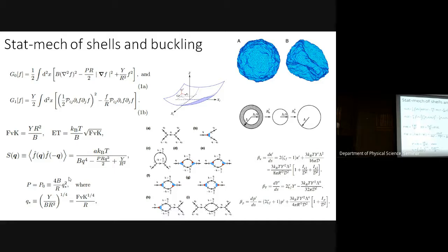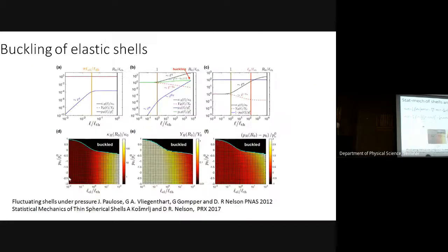Once you do that, you get buckling. So once you do that, what you see is that the thermal buckling, the buckling that was there in the linear theory, changes depending on your temperature, and sometimes changes quite drastically. Over here, I am plotting, for example, the critical buckling pressure, and you see for small temperature, it is 1. And that basically means what you would get from the theory of shells in mechanics.